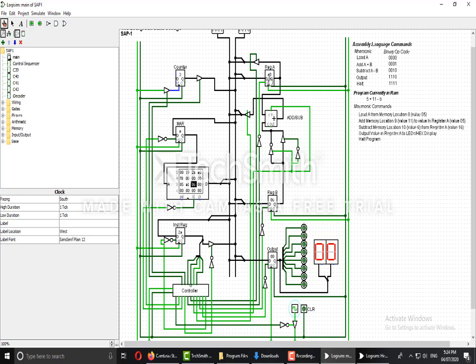Now at register A we have A0 because 06 is subtracted from A6. Now the next instruction, program counter is incremented by 1. So the next instruction is at location 3 or the 4th location, E0. E is for output, and the lower nibble 0000 is a no care condition. So even if there is any other number, it would still not matter. So we are only interested in E.